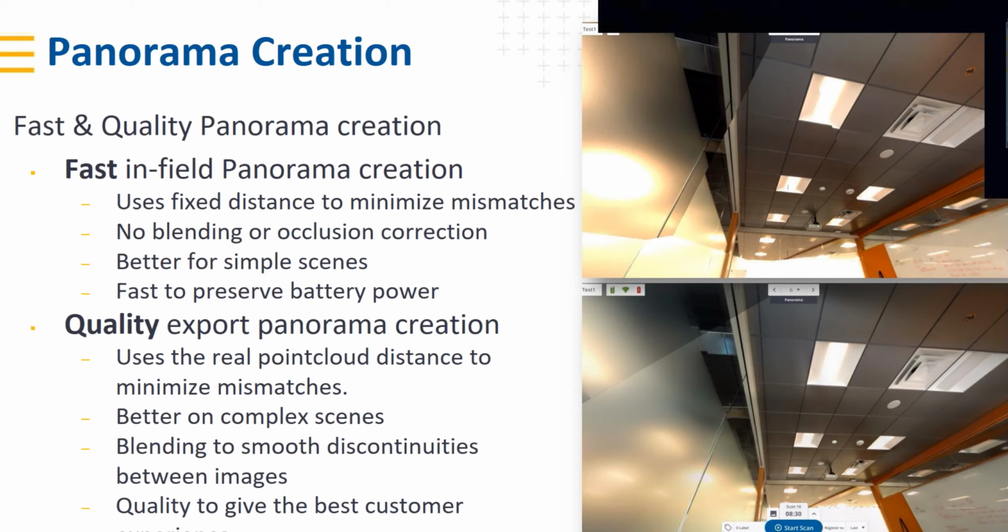Now, in the scanner software, in the field perspective software itself, you have the capability to either turn on or turn off the processing of the images, not just to take them, but also the processing. So you can have the processing on as you go along and scan. We would normally recommend people to do that as part of the export at the end, simply because it eats processing power, and it also eats battery power while it goes on and does that.